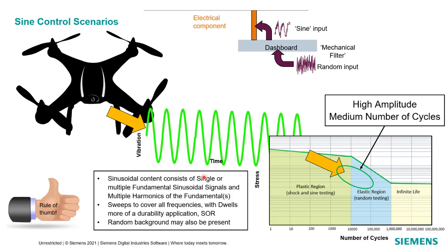This would typically involve modes, but we're going to focus on the sine sweep. You'll have some sinusoidal content in a sine sweep, and this can generate the fundamental sine frequency but also the multiple harmonics of that. If there are harmonics in the responses, you can get those, and that's part of the signal that is measured.